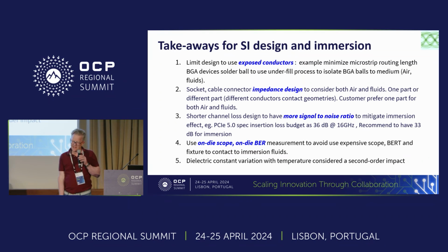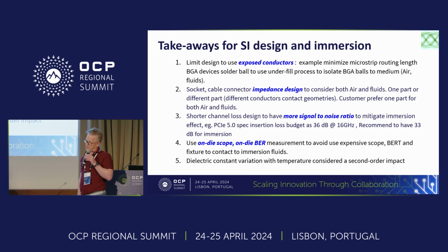Okay, so takeaways. As you can probably tell, it's best to avoid issues. So in design, avoiding the exposed conductors, like that strip line that we showed you before. Embedding things within solid dielectrics is really doing a great job of avoiding the issue of immersion. Designing things with consideration for the properties, and you saw the Intel base spec for the fluids, so considering those in your design processes for components is also a good avoidance strategy. Increasing the signal to noise ratio, of course, it's fundamental, is going to increase your chances.